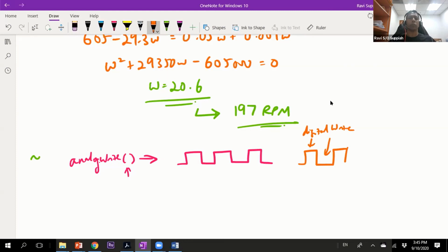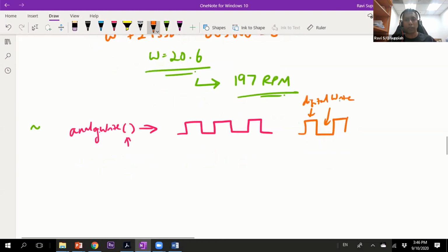That is a more tedious and very inefficient approach. As much as possible, if you're doing a project on your own, you should allocate a PWM pin for such operations, so your code is a lot neater and easier to handle.